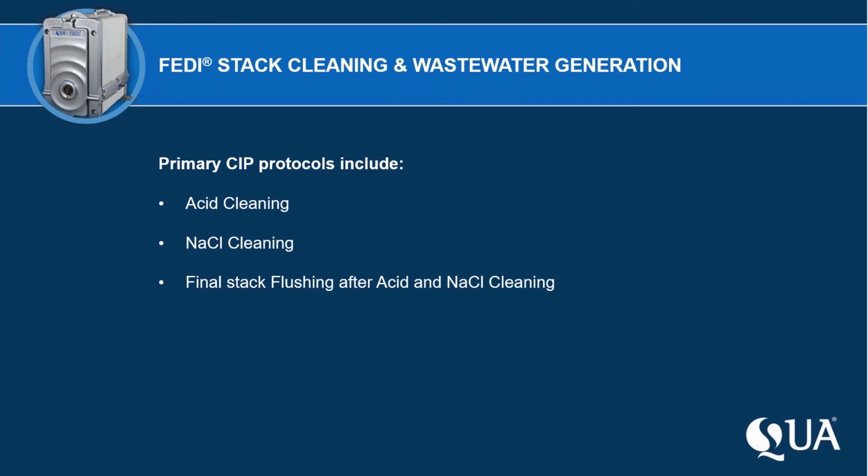CIP protocols are similar to others out there. Most of our stacks we don't require cleaning, just because of our design. If needed, acid cleaning for any type of mineral deposits. And I find sodium chloride is actually very effective. Sodium chloride is probably one of the more effective, and it's not a hazardous chemical. And then we always require flushing afterwards.